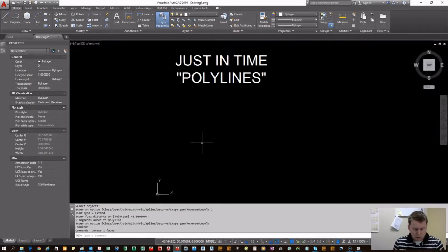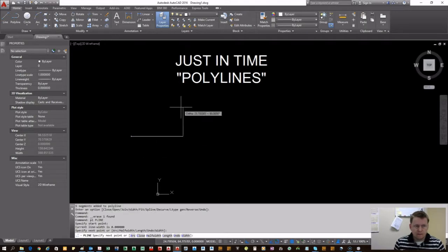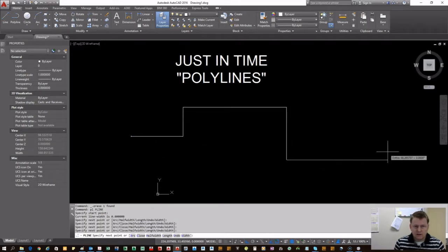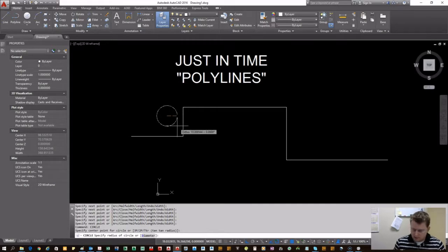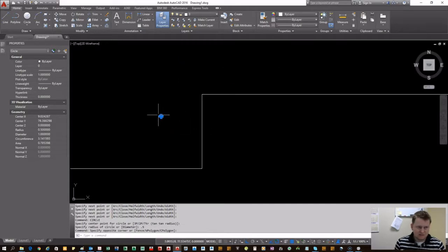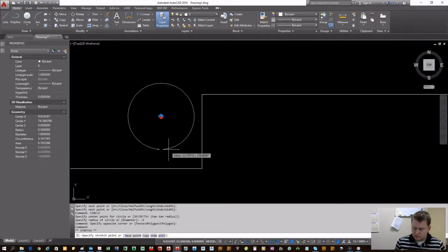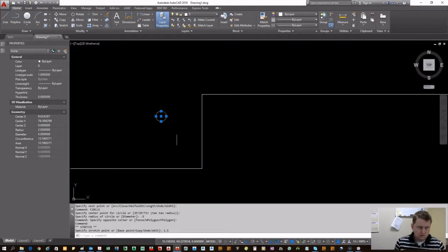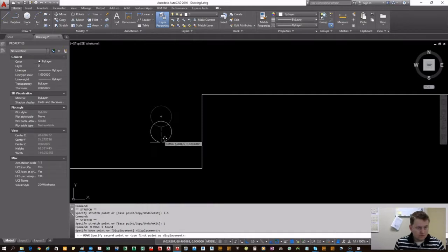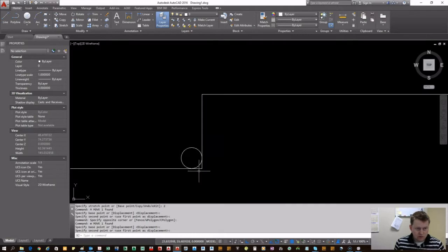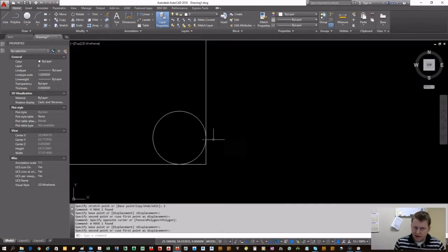Okay. Polylines are also useful and speed up a process because, unlike regular line work, say if I wanted to fillet this line, and I know that I want, let's say, a half inch. That's a little bit small for what we're doing. Let's say 4 inches. Okay. So I'm going to move these based on their quadrants, so I know I want the arc to look like that.